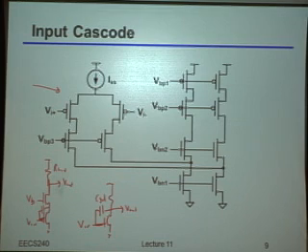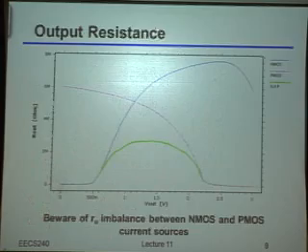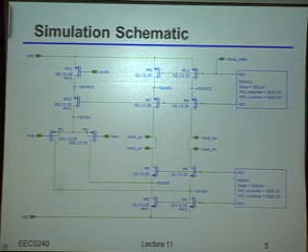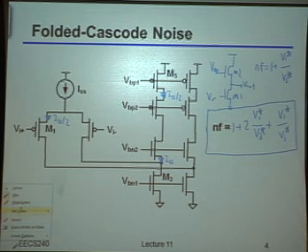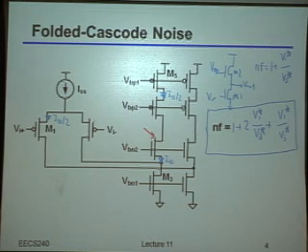But again, in order to make sure we understand why that is, we have to do a little bit of a reminder. Let me ask you guys a question to see if we can pick off why that at first seems a little bit funny. Let's say we go back to this original folded cascode OTA, where here I do not have that input cascode. Oftentimes, people look at this and say, well, I don't get it. Why would you add a cascode into the input device? Because, hey, we already have a cascode over there on the output, so the input device is already going into a cascode.